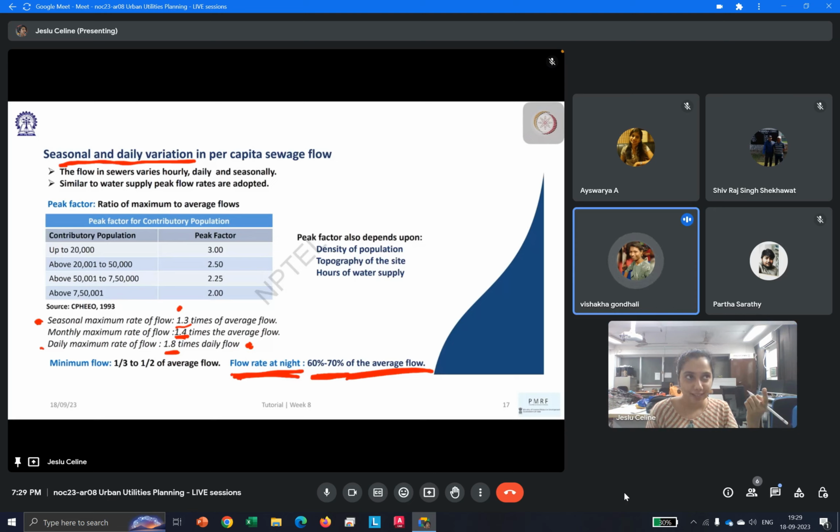Fire supply related. Okay, yes, I think fire supply we saw, but mainly water supply related. Yes, when we were calculating the water demand, I understood you said fire because that's involved in the process of calculating water demand. You're right. So there we saw when we are calculating water demand, we will take 1.5 times the monthly maximum to be the daily maximum. So it's the same thing.